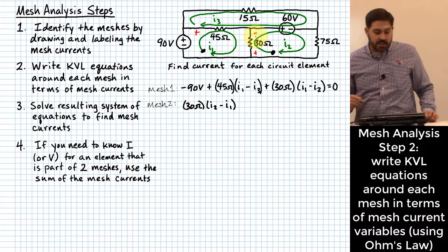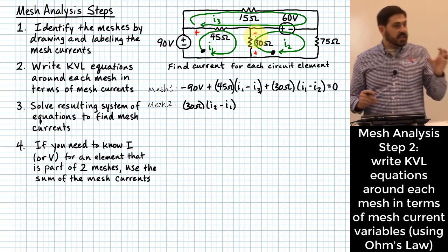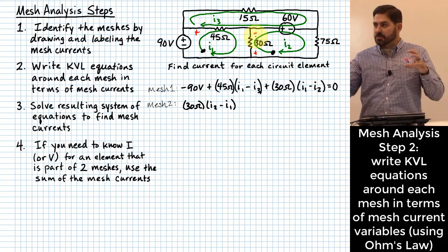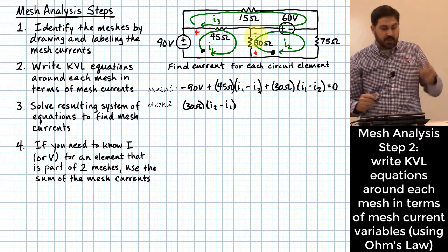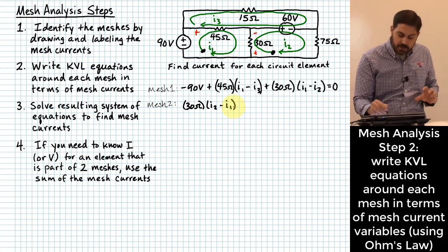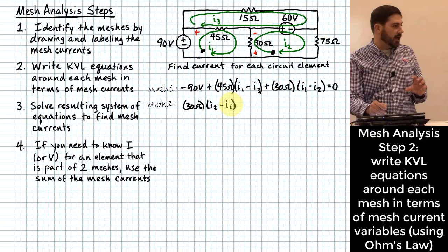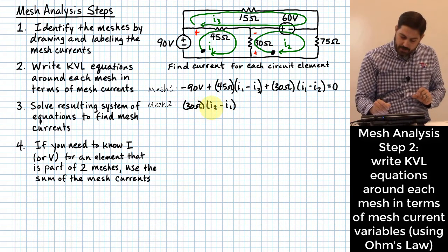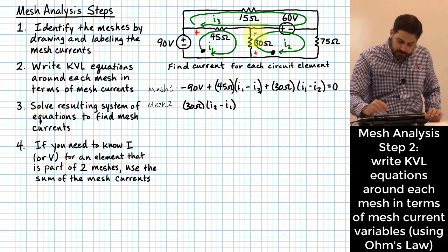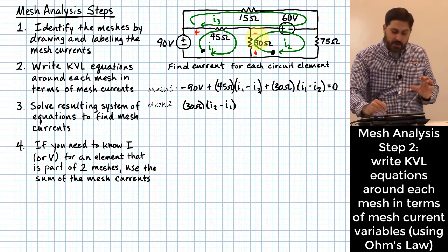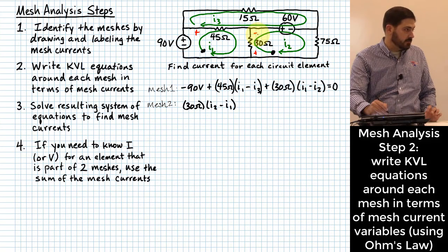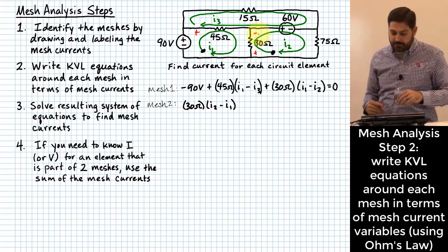And this is not inconsistent with the last one I did, because each one of these sums can be done separately. Even though I'm assuming that voltage is opposite in this sum than I did on the last sum, it doesn't matter, because all I have to do is make sure it's consistent with the term that I'm writing in that instance. So this term assumes that I2 minus I1 gives you a current that flows upward, and that would assume that a voltage was positive on the bottom side and negative on the top side. So I'm consistent internally with what I'm doing in this sum.